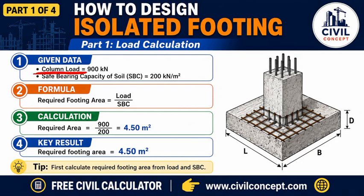Here, the column load is 900 kN and the safe bearing capacity of soil, also called SBC, is 200 kN per square meter. First, we calculate the required footing area. Required footing area equals load divided by SBC. So, required area equals 900 divided by 200. Required area equals 4.50 square meter.